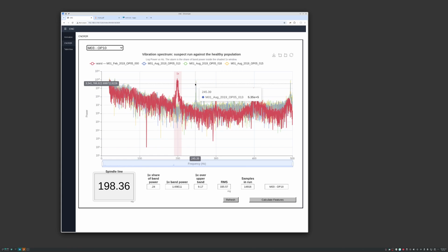And so that points out a shortcoming of the data. The vibration data is not necessarily a sufficient data set to determine the answer to this question. What we really need to know is the speed of the drive. Was this really running at 200 hertz, or was this really running at 250 hertz?